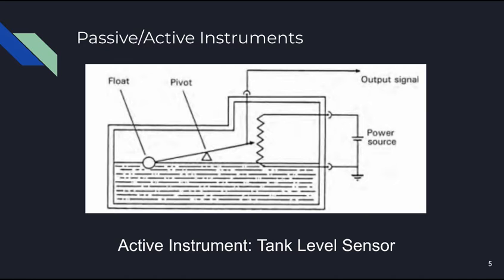In an active instrument, however, adjustment of the magnitude of the external energy input allows much greater control over measurement resolution. While the scope for improving measurement resolution is much greater, incidentally, it is not infinite because of limitations placed on the magnitude of the external energy input, in consideration of heating effects, and also for safety reasons.